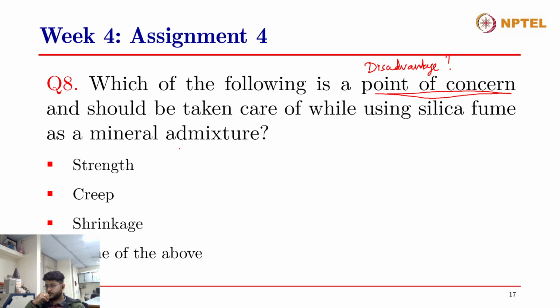Sir, it's creep or shrinkage. Of course, it is going to be creep or shrinkage because we have already ruled out strength. You have to pick one, and you have to mention why. Shrinkage, sir. Okay, thank you. But how do you say that addition of a high volume of silica fume in concrete increases the shrinkage? You mean to say that the disadvantage is that shrinkage gets increased, right? Yes. How does it increase the shrinkage?